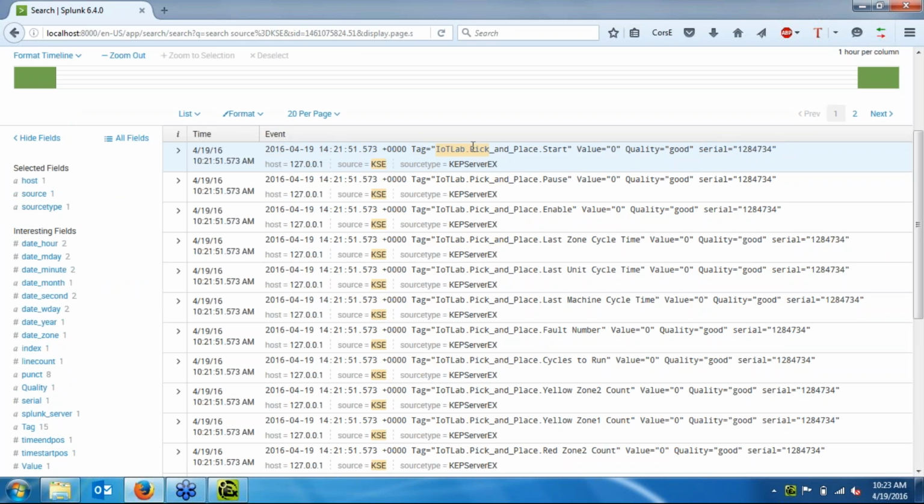So you can see each data change event from a tag is going to create a name, the tag, the value of that data point, and the quality of that data point based on the event or the poll that KEPServer has of that particular tag. And additionally, what's also important is we have the timestamp of when KEPServer EX received that data from the device.